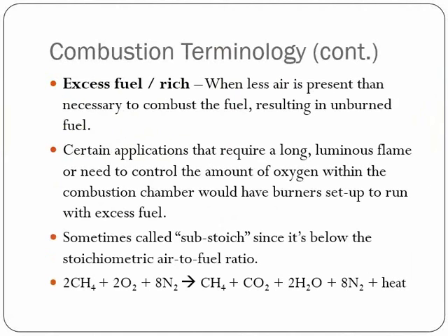The opposite of excess air would be excess fuel. This can sometimes be described as a rich running flame or rich combustion. So this is when actually less air is present than necessary to combust the fuel. And by present, I mean being introduced into the burner itself. All the fuel eventually is combusted, but what happens with excess fuel applications is they may want to, instead of forcing all the combustion air through the burner, have the flame and the fuel react with the chamber that it's firing into and use the oxygen that's available inside that chamber.